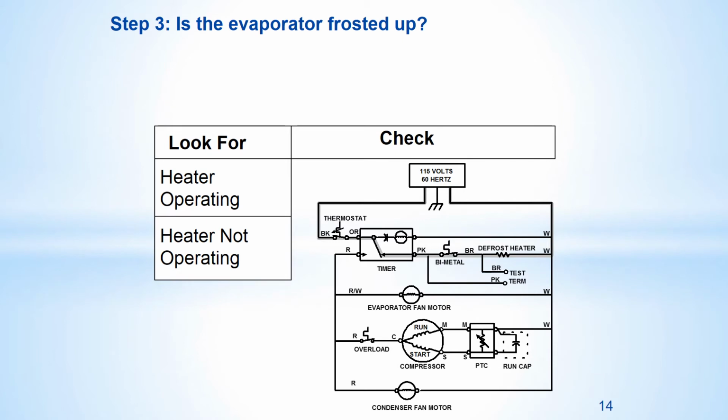A reason for lack of internal airflow can be a failed defrost system. Frost buildup on the evaporator coil will also reduce heat transfer. In this scenario, you have determined a lack of airflow due to the excessive frost on the evaporator cover, and you have advanced the timer manually to initiate a defrost cycle. Now, how do you determine if the heater is actually operating? The answer to that question is to check for heater current. Place your ammeter anywhere in the heater circuit that is convenient.